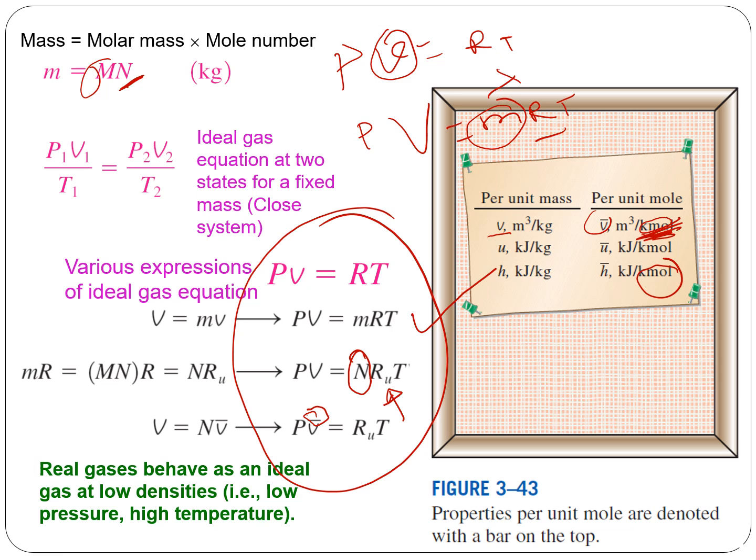And now, when can you use this equation? As the name suggests, ideal gas. What is an ideal gas? It's just a hypothetical gas, right? So this equation can only be used when pressure is low and temperature is high. When you have low pressure and high temperature, the ideal gas equation still gives you a good result.